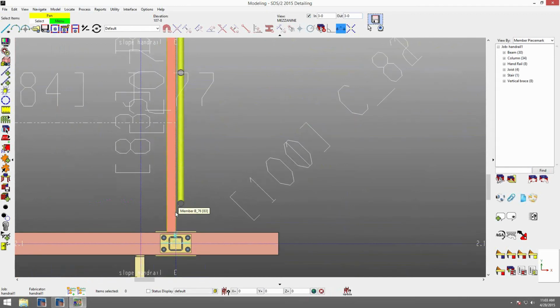I want half of the outside of the diameter for the pipe, so this was like 1.5. So the outside of the diameter was 1.9, and then I divided by 2 plus the plate thickness that I want to use of 1/2. So I offset this over 1 7/16.